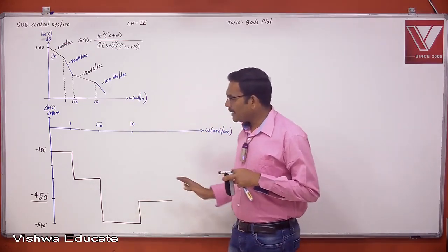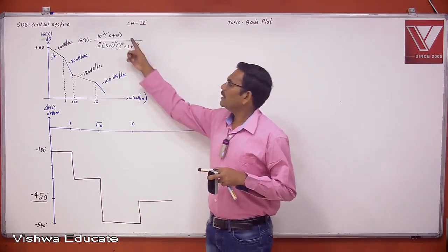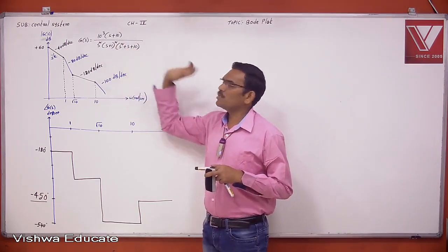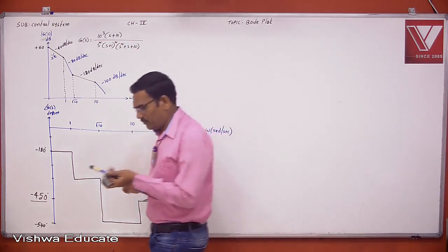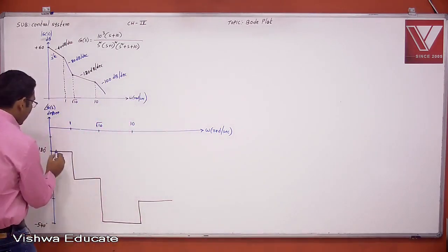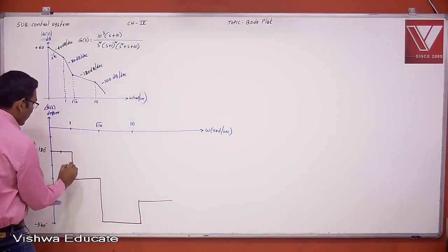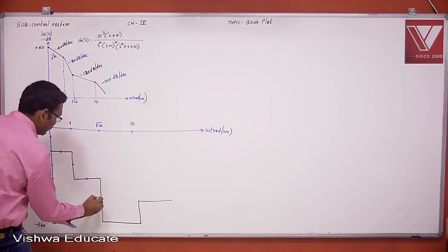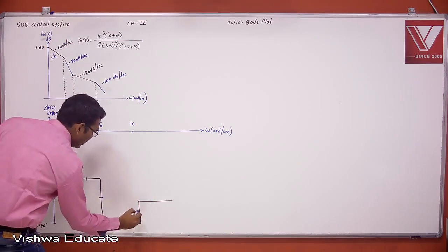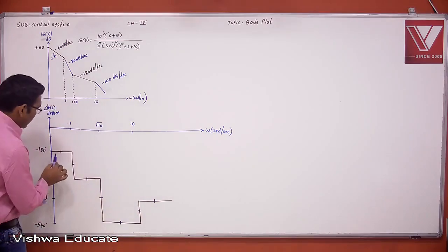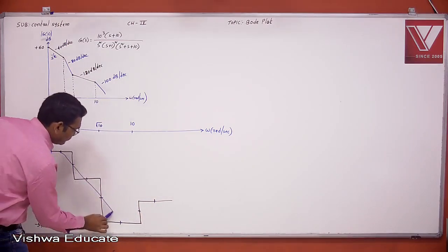So you should write like that, and after that, for a transfer function consisting of simple poles and simple zeros, you should draw the phase diagram like this. Take all these horizontal and vertical line center points, and by touching all these center points, draw a smooth curve.